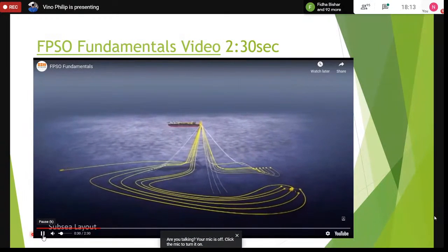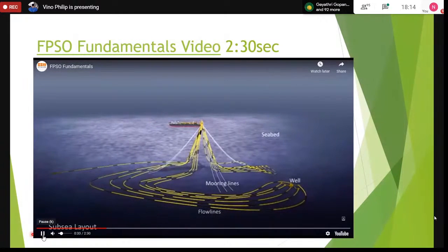Now you will see kind of like the flow pattern. So like I explained, the mooring line, this is the seabed, this is the actual soil. The sea is above, this plane right above here. And this is the actual well through which the oil is coming. And then from the well, there is a jumper, or it's called a spool or a jumper, to the PLEM, the pipeline end manifold. And this over here, where the pipeline starts, is called the pipeline end termination, the PLET.